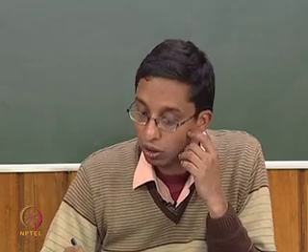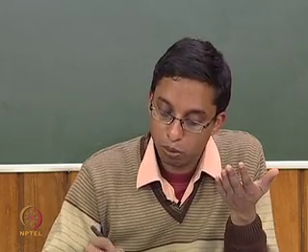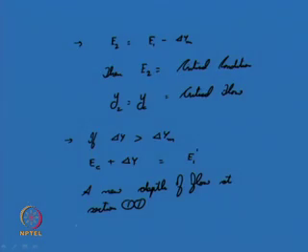Now, you can see how the critical flow is being applied here. If the flow, a subcritical flow in a channel section, if there arises a hump, you will see that the minimum possible is that flow will become critical at section 2.